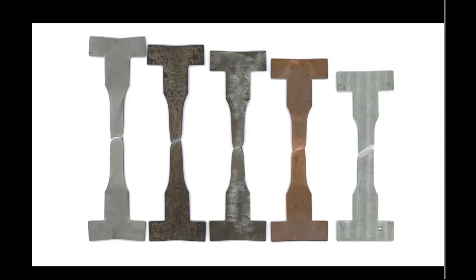What you could see, even visually, is that the annealed steel, or 1020, has been heated and then left to cool down. With heating and cooling down, the stresses are released and the steel becomes relieved. So it's relaxed, and it actually shows slightly longer elongation compared to plain, untreated, as-processed cold rolled steel.